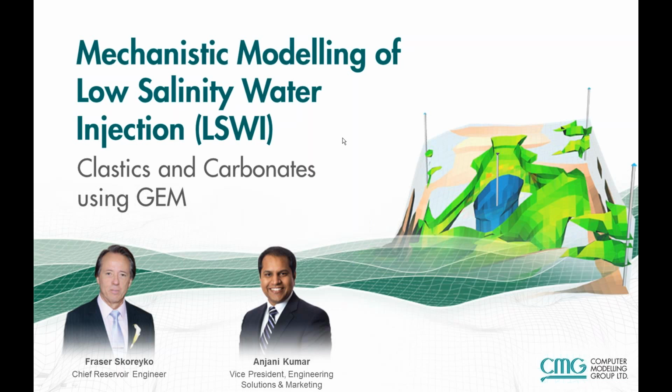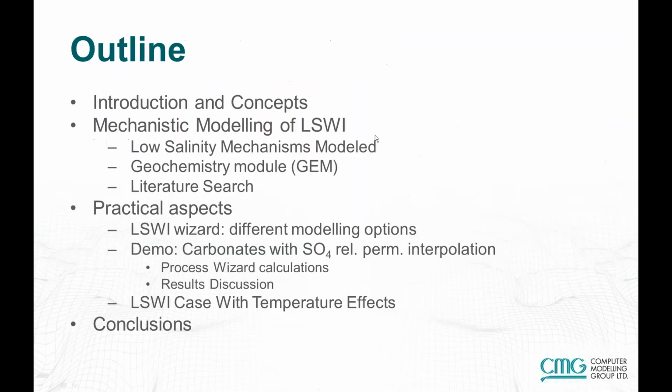Thank you, Anjani. The outline of this webinar will be, first of all, introduction and concepts, then mechanistic modeling of low salinity water injection, or LSWI. Then midway through, we'll switch to some practical aspects. We'll look at the wizard that's in Builder for this process and go through a quick demo for carbonates with SO4. And we'll look at the same case with temperature effects and then conclusions.